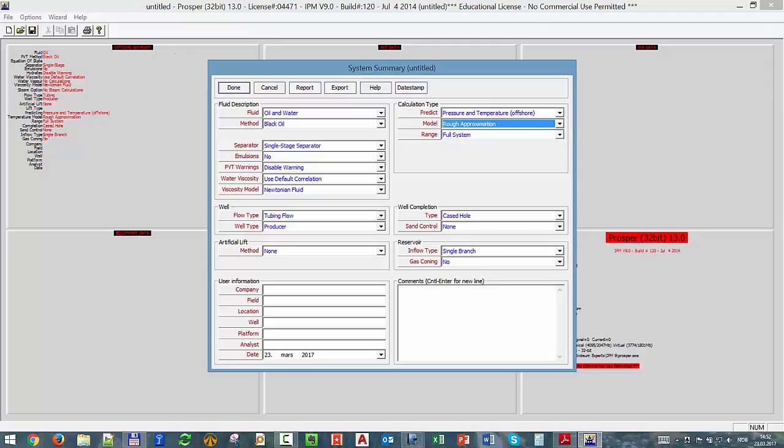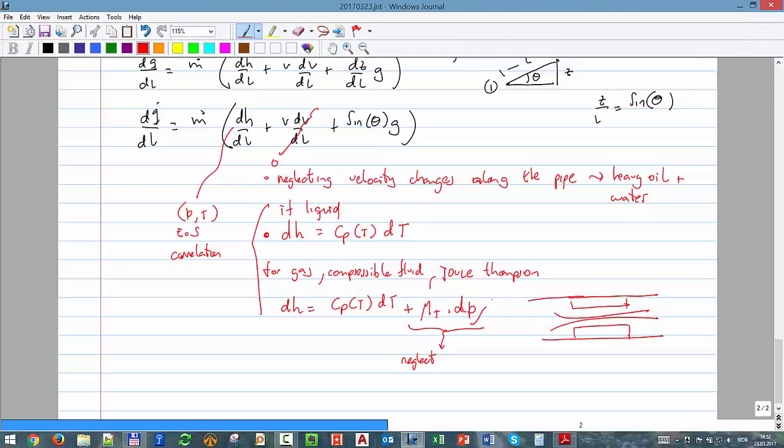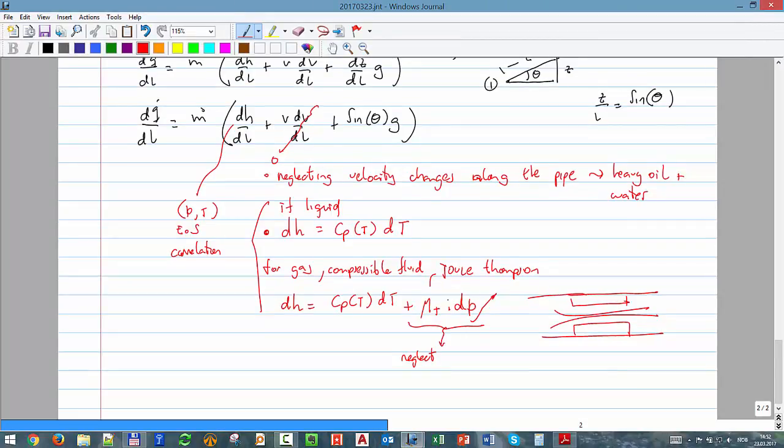so you can specify, because it really saves some time to neglect that term. Okay, trying to compute that term is kind of a bit cumbersome. So I neglect all of that. I substitute the rest in that equation. So I have dq dl equal to mass flow of cp dt dl plus sine of theta g. Okay, and then I have to plug in the heat.